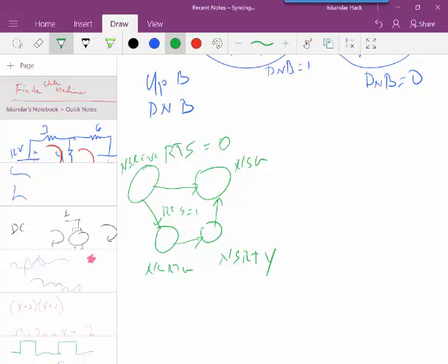So we look at this right turn sensor. If it's a 1, we go through these two states, then we do the normal right turn motion right there. If there are no cars wanting to turn right, we skip that state.